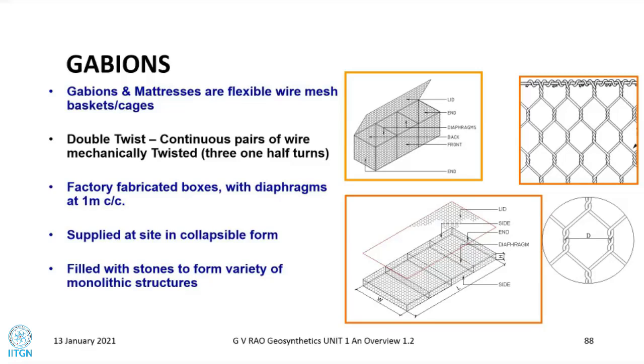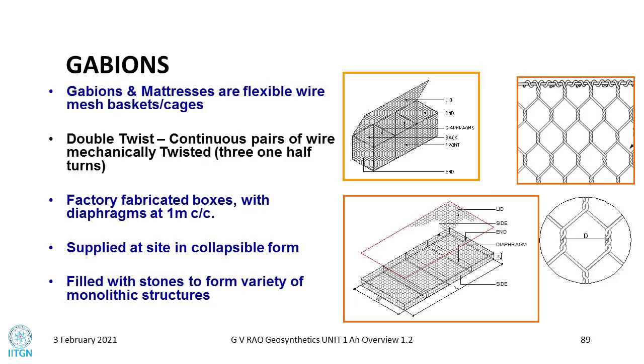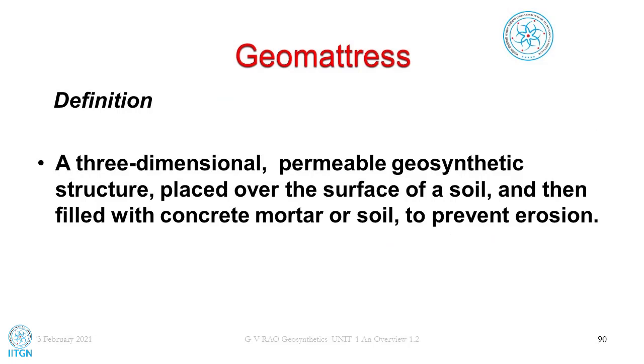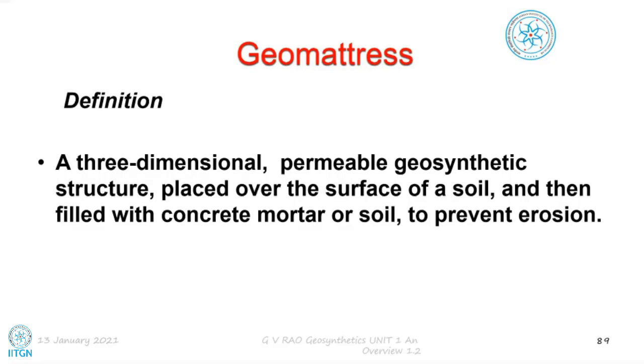And this mesh itself can be used for reinforcement, and boxes can be used for fascia. And these are a last kind of material as material now. What's going to happen is this can be placed, let's say, on a slope, on a river bank or in a canal also, and it's double layered. And in that we can now pump in concrete or cement sand mixture. It flows over that and can get into the bed of the canal also, get to the uneven slopes on the side also. And once set, it becomes a permanent layer, and that layer is called a geomattress actually.